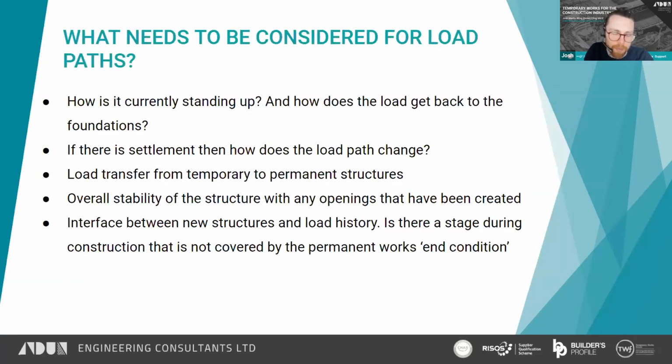So here we've got a few items that need to be considered when it comes to load paths. How is the structure currently standing up? Chase the load all the way from the top to the bottom where the foundations are and justify to yourself how this structure is able to remain standing. How does the load path change if there's any settlement? If a support drops, then where does the load go? Is there any redundancy? Is that an issue? Sometimes this isn't the case when a structure is being demolished anyway, but that needs considering.